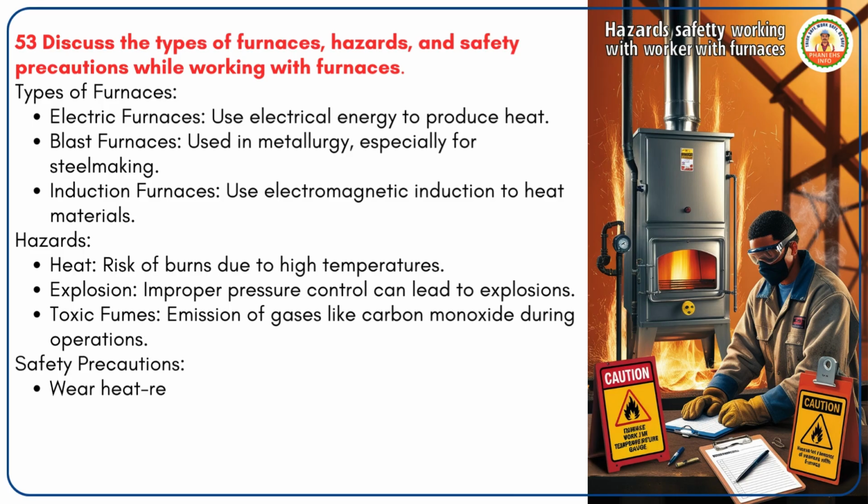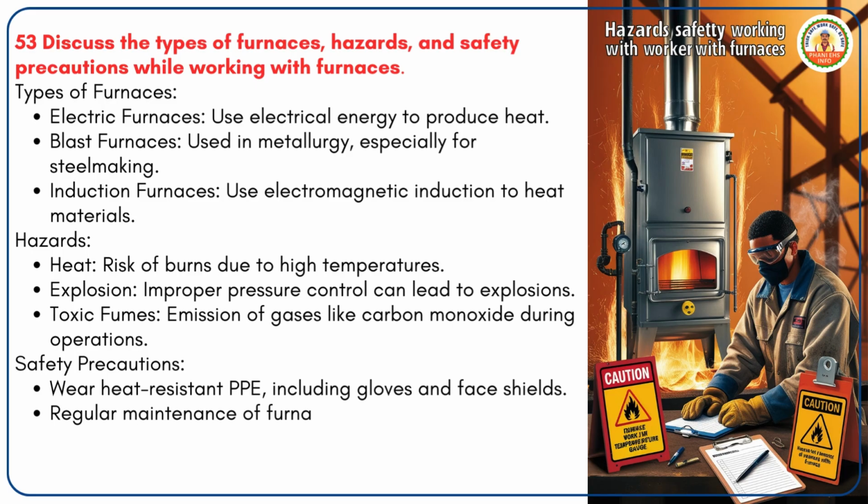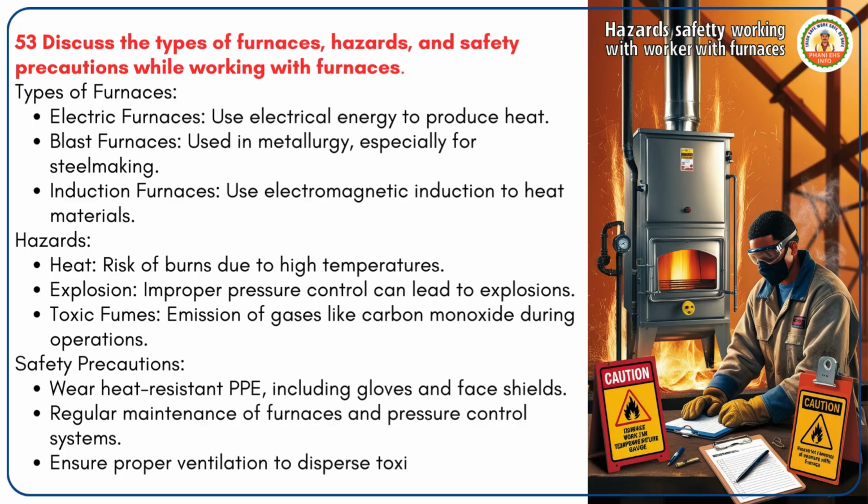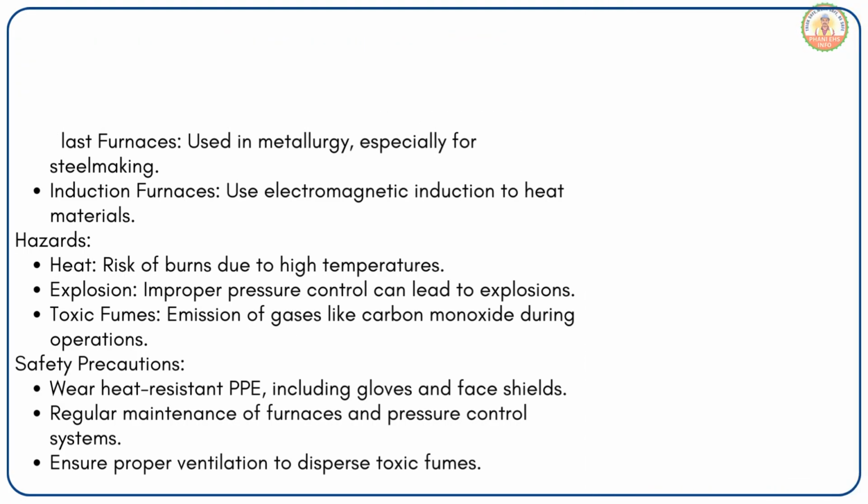Safety precautions. Wear heat-resistant PPE, including gloves and face shields. Regular maintenance of furnaces and pressure control systems. Ensure proper ventilation to disperse toxic fumes.